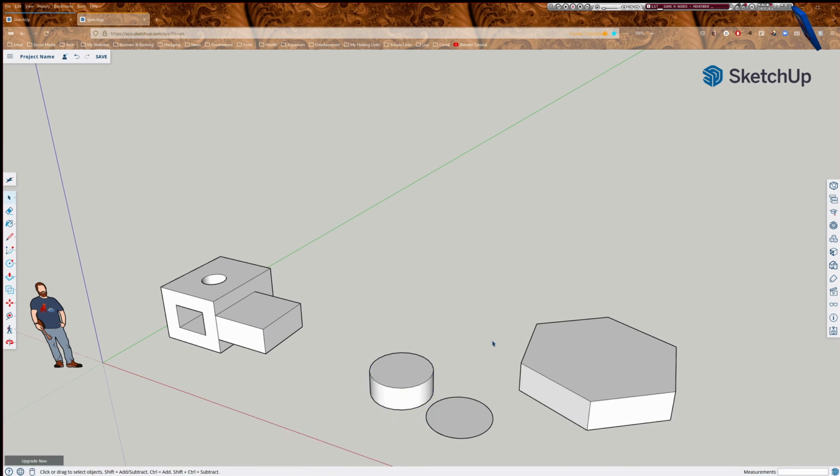But if I go from right to left, anything that line touches, it'll select. So if I come this way, you'll notice that the outline is now dotted. And now everything it touched, it's selected. So this is an important difference, and there are different times when you need these different capabilities. So they've really done a good job with keeping this interface simple. Okay, so now if we go back here and we try and select everything.